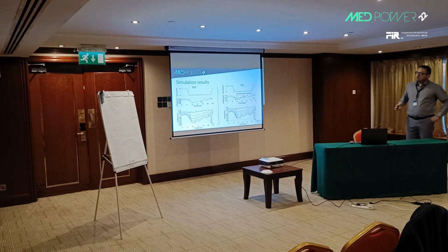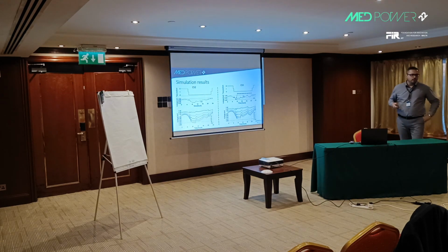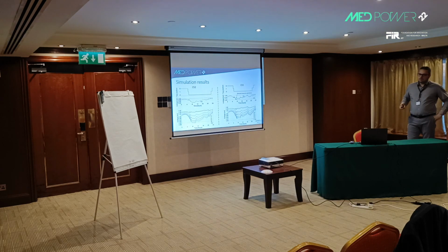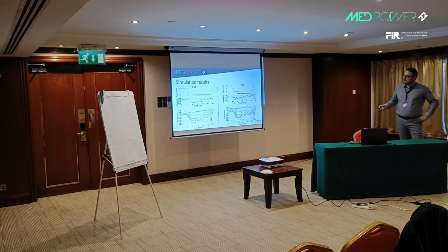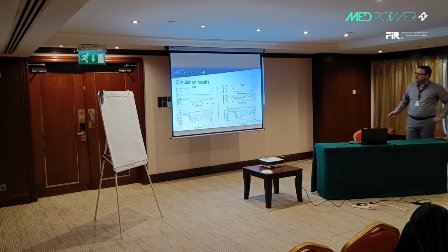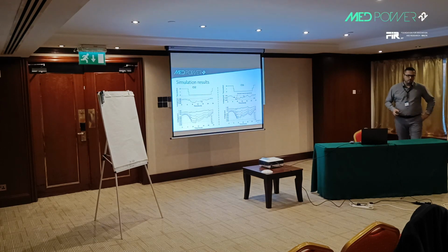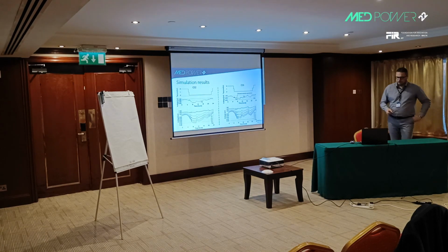The combination of the operation of the LTC of the medium voltage, low voltage transformer with demand response actions is the voltage control measure that brings the voltages into the normal operation area. However, we can see that there is an amount that is shed from the consumers.